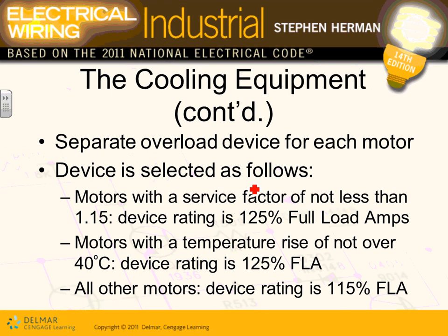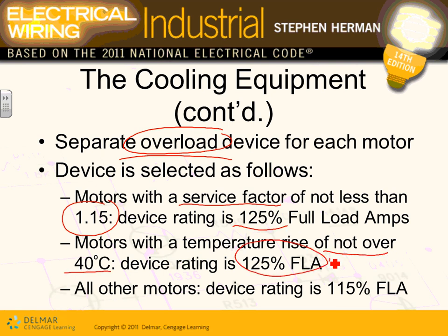That's a coil that they use. If you're to use overloads, you guys have done this overload sizing for me. The manufacturer, you're very familiar with this one. Service factor, you guys remember the term service factor? You did it with your friends, 150 or 125. If the temperature rise is not over 40, your multiplier is 125. In all other cases, your multiplier is 150. You were tested on this, if you recall.